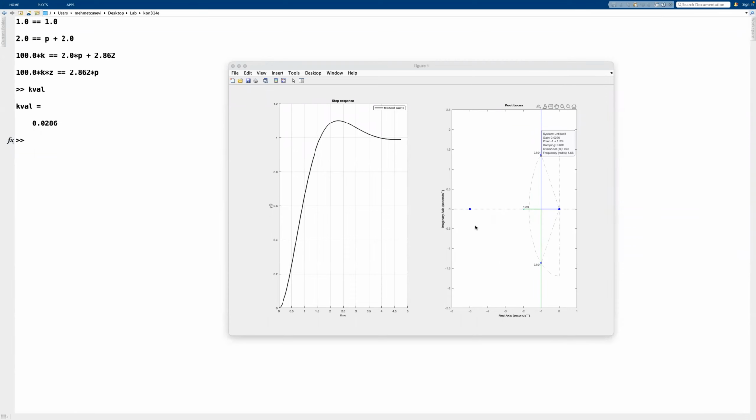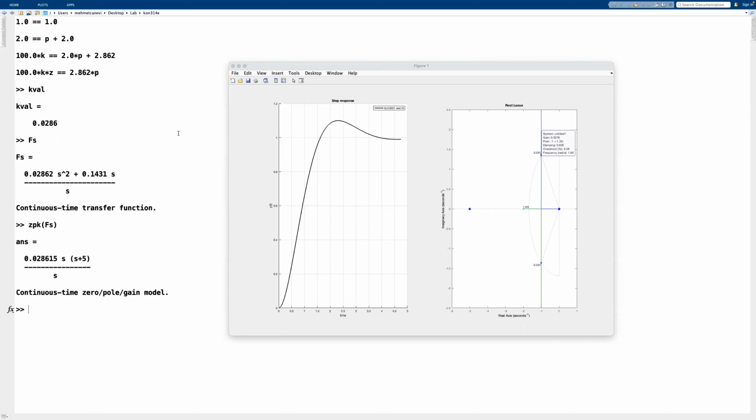Now, this is probably the best way of designing a PID controller, because it gets rid of the unnecessary stuff and you end up with only two poles, which are the conjugate ones, so infinite dominance factor because you have nothing else to worry about. But that's not actually it, because if you look closer at your controller, you didn't actually design a PID controller at all, because your controller has a pole at the origin and a zero at the origin. So this cannot, of course, happen.